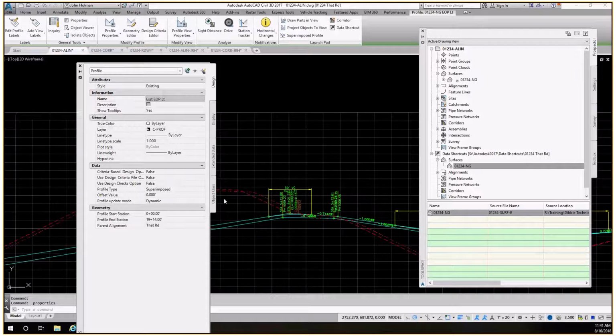That tells me that that is an existing surface, which I want to see first, just so that there's absolutely no confusion when you're bringing shortcuts in as to what's a proposed or an existing profile. That's the first priority for me. So exist EOP, edge of pavement left, and I don't know how anyone could confuse that.